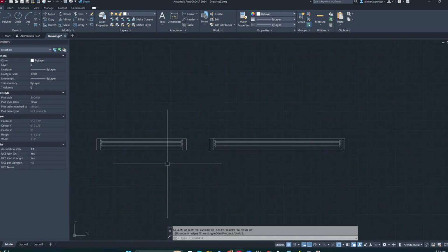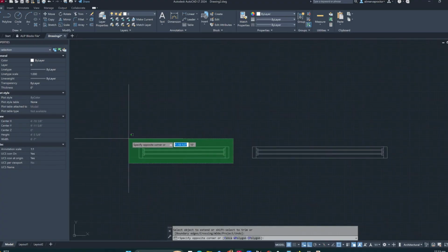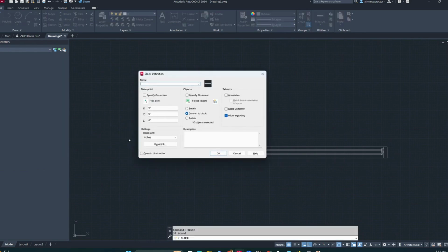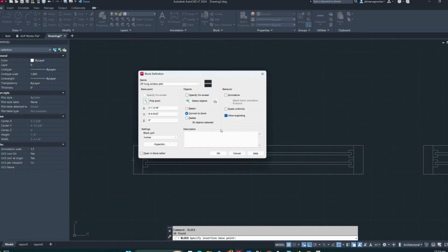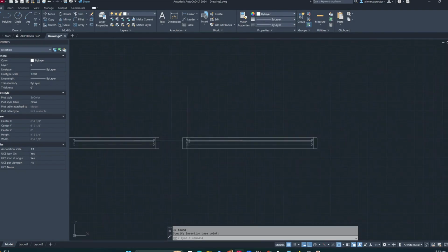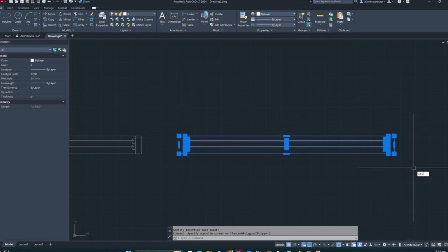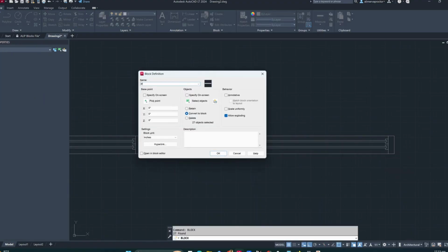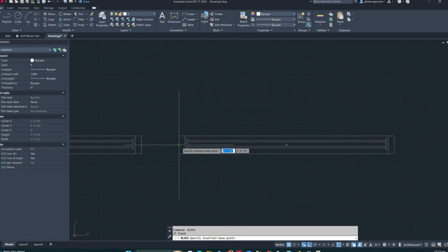Right, so now we already have our louver window, our 2 feet, and our 3 feet in plan. So you know what we're gonna do. We're gonna highlight this, type block, right? Sorry, not louver. Sorry, our hang window, 2 feet, hang window plan, pick a point, pick this point. Okay. Same thing we do over here, highlight, block, 3 feet, hang window plan, pick a point, click right there.